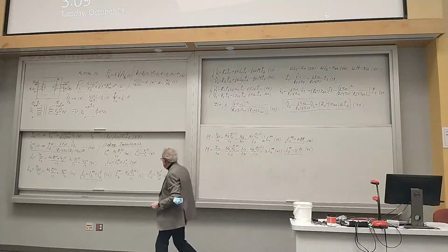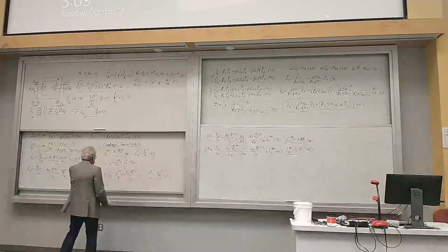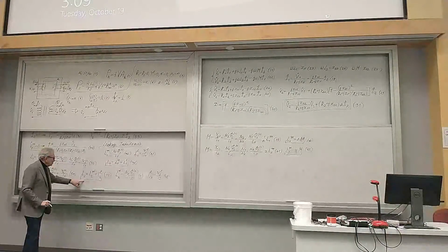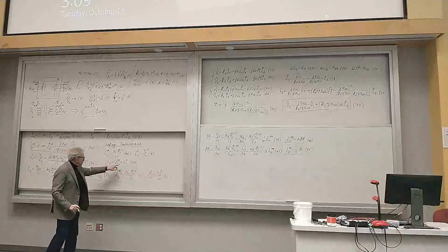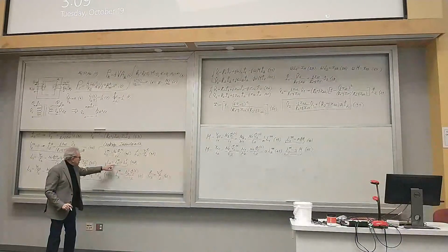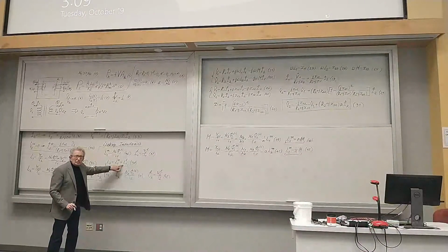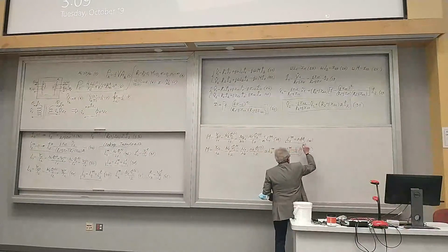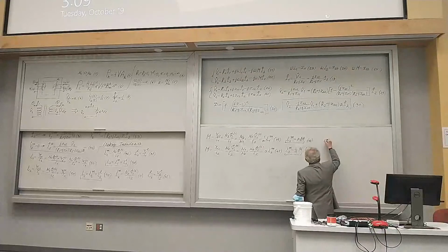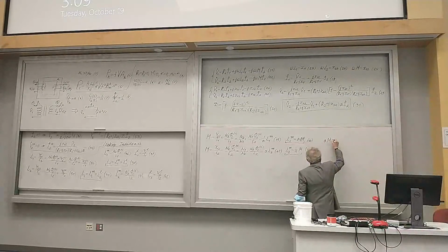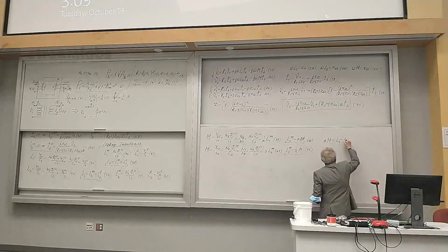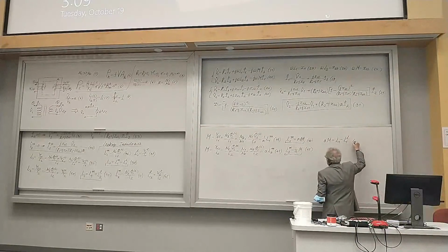Then I will go to these formulas, 38 and 40. According to 38, this main reactance is equal to the difference of these. But at the same time, this main reactance is equal to aM. So you can write that aM, which is the main reactance, will be equal to the total primary inductance minus the leakage inductance.